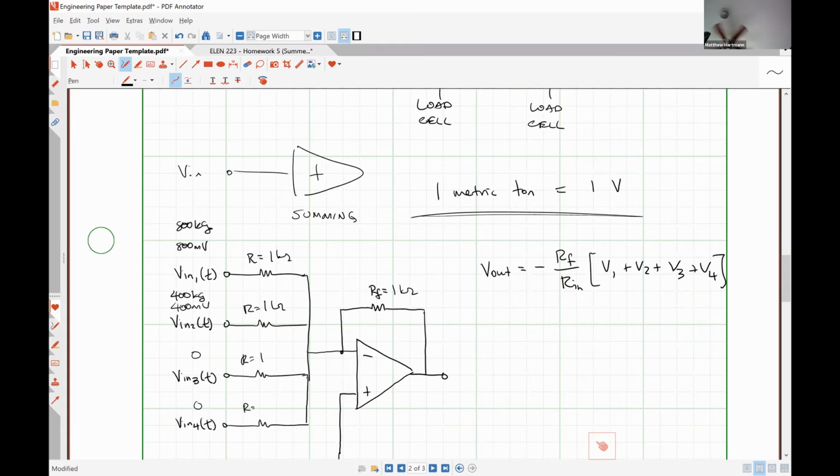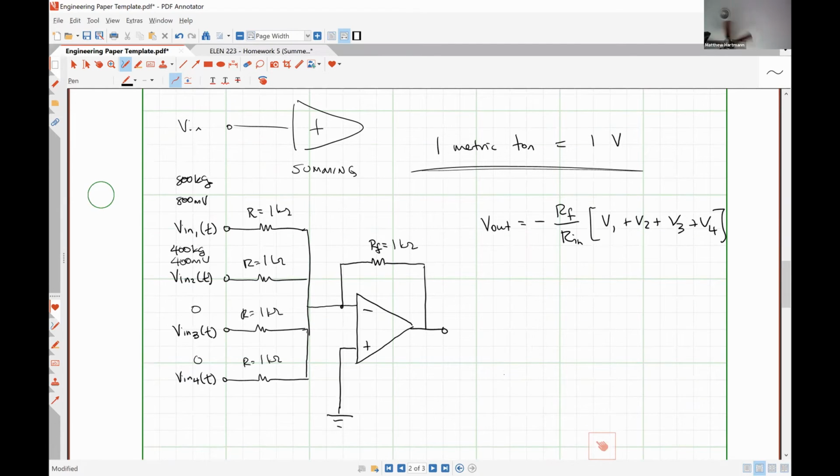So how would we fix that? Could you just measure the input voltage negative? Sorry, 2 people were talking and I heard something about just negative. Go ahead, Dan. I was gonna say, could you just use another op amp? Yes. So what kind of op amp would we use? An inverter? Okay, so we'll use an inverting op amp.